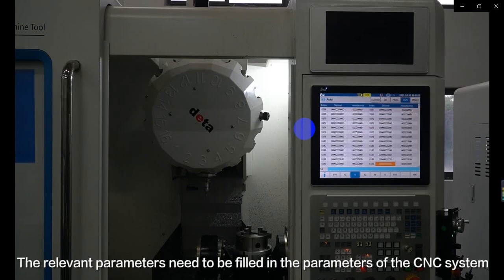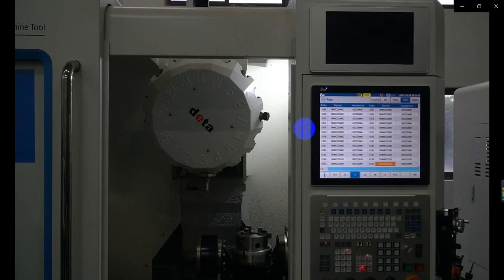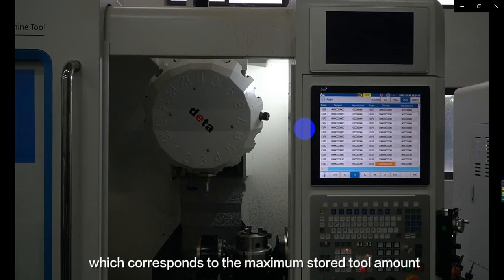The relevant parameters need to be filled in the parameters of the CNC system. The number in the B187 register is 16, which corresponds to the maximum stored tool amount.